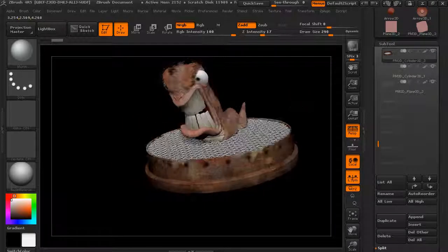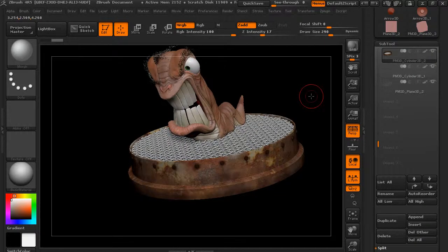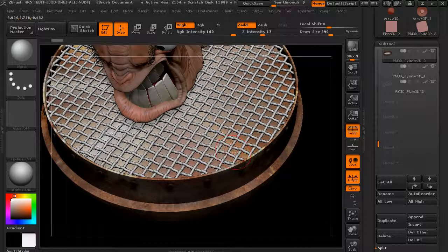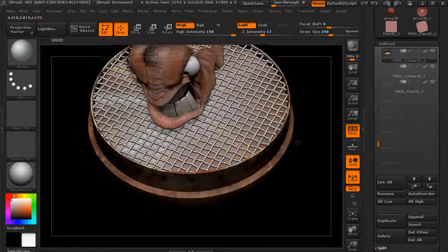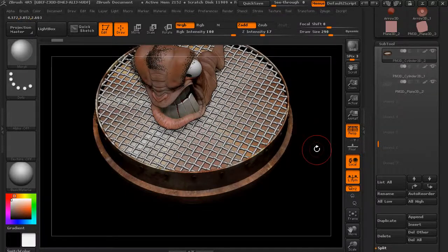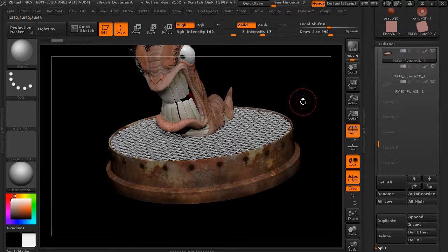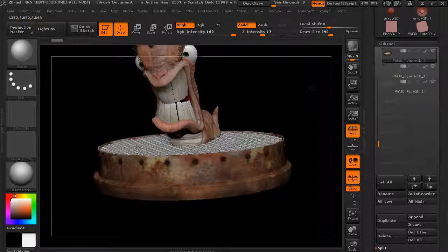Okay, so that's kind of cool. You can come up with a lot of different options for how you want to build geometry to use as your micromesh and be creative with those. You can see I've created a section here that kind of has it overlapping, so it kind of goes up and down, up and down. But if you want to just have a kind of a mesh that's connected, you can do that as well. All right, so that is how we can use micromesh and convert to geometry to be able to use.